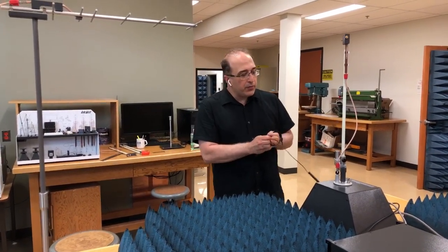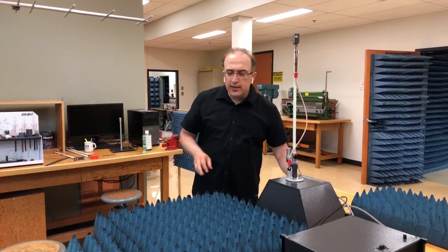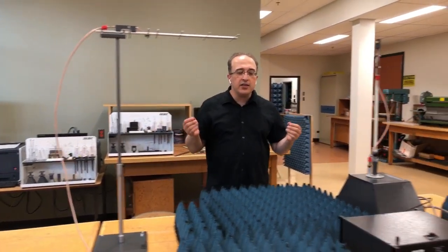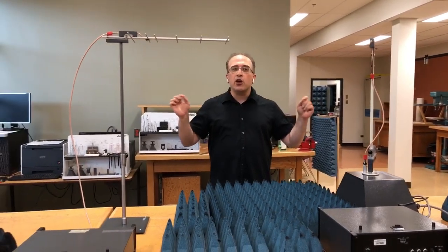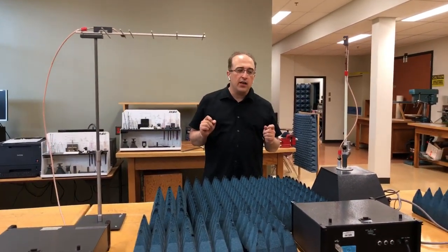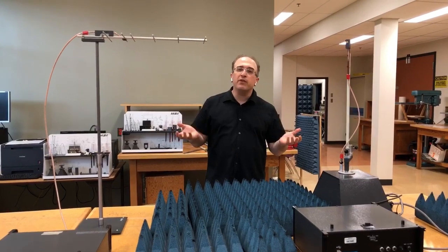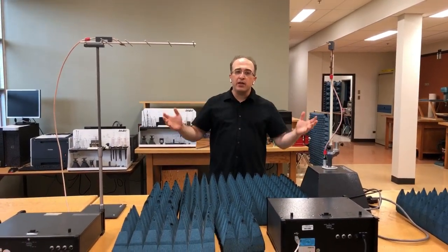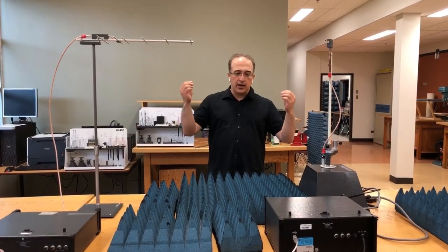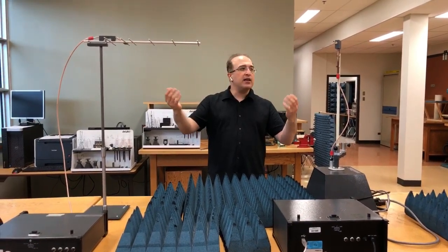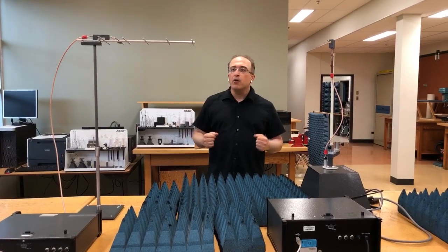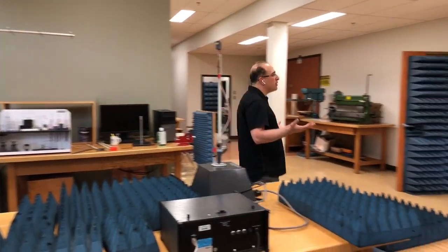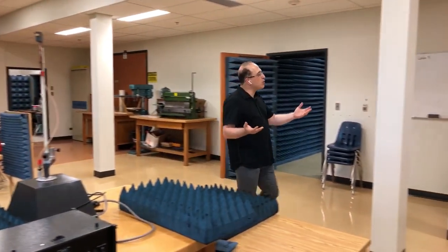When you are working with this type of system, you need to make sure that you wear the wristband. Now, the other thing to note is that when we are measuring the radiation pattern, we might see some fluctuation in the radiation pattern. Part of that could be due to reflection from the walls. Ideally, you want to measure in a free-space environment, when it's just about the transmit antenna and the receive antenna. But if you look at our room right now, for example, we have this column right here.